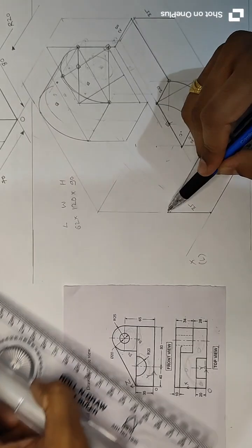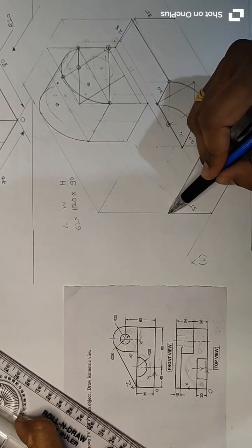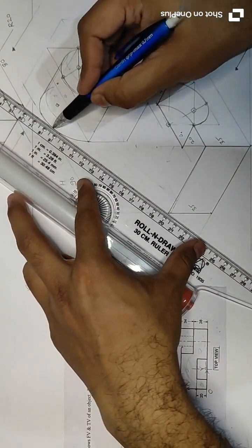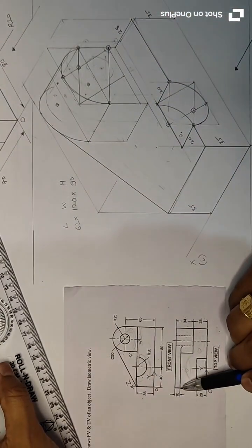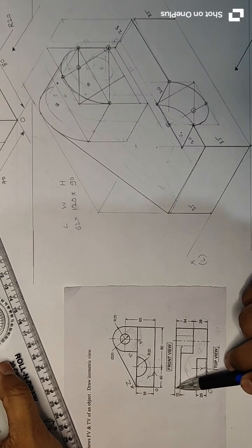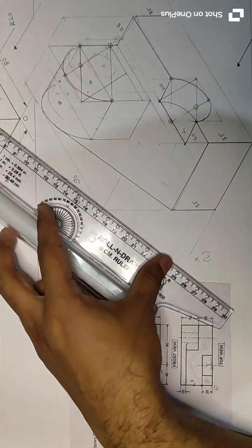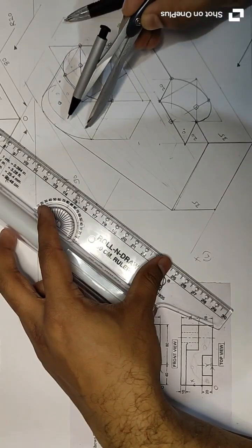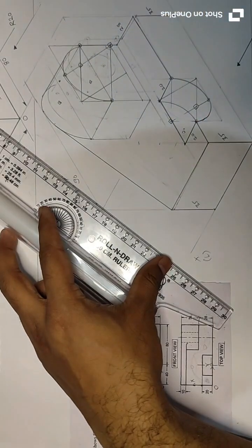Then this is a fillet part. This triangular part is the fillet part. So we will join this point with this circle. And at 10 mm distance, this fillet has a 10 mm width. So again at 10 mm distance there is again one inclined line. But to draw this inclined line, first we will translate this part of the quarter circle at a distance equal to 34 minus 10, that is at 24 mm distance.